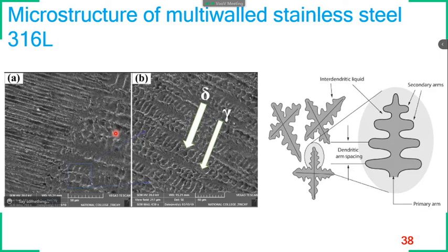But you may ask me a question. These coarser grains are not that suitable for tensile or fatigue applications. It is not that good. Then how can WAAM become a suitable option? WAAM can become a suitable option for high temperature creep resistance applications, because high temperature creep resistant applications inherently need a coarser grain.